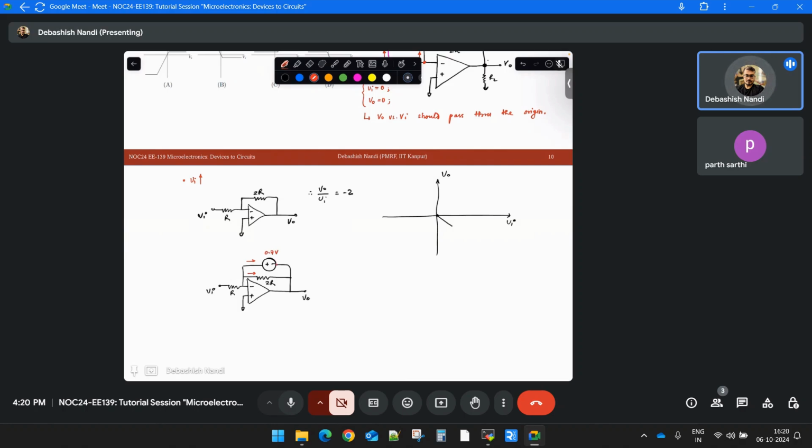What is the series resistance of an ideal voltage source? Infinite. Are you sure? No, sir. The series resistance of an ideal voltage source is zero, right? If it were infinite, everything would drop there. Exactly, sorry. Infinite will be an open circuit only, right?